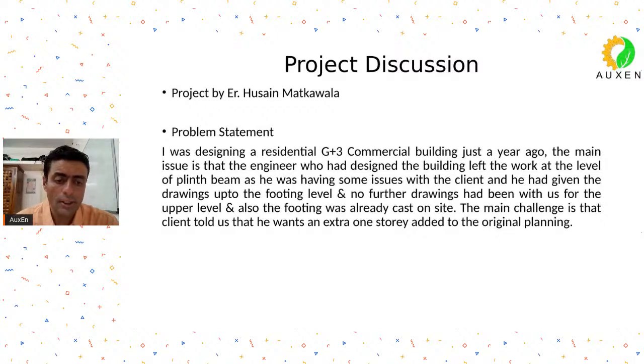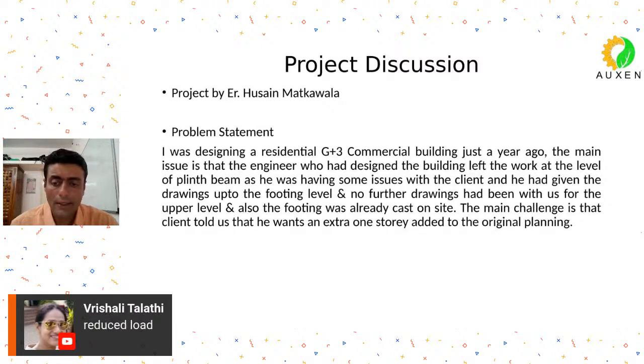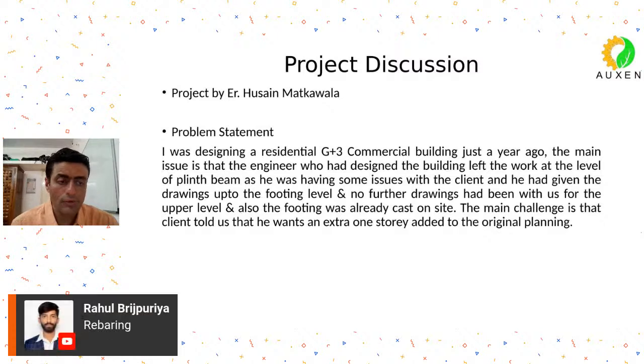Okay. The only thing that you can do in case the bearing pressure below your footings increases or goes beyond the bearing capacity is to excavate the footing and increase its plan area. That is the only option you have. There is no other possible solution for it. So you will have to excavate, you will have to reach the footing level, you will have to increase the plan area of your footing.